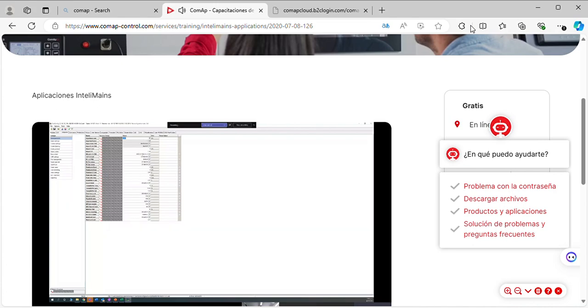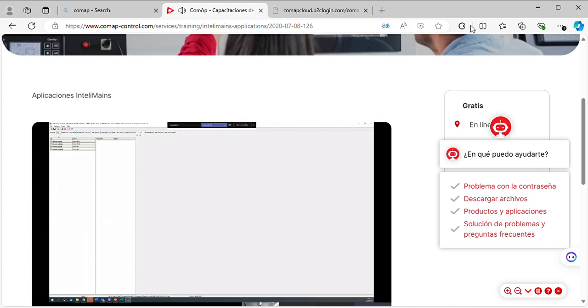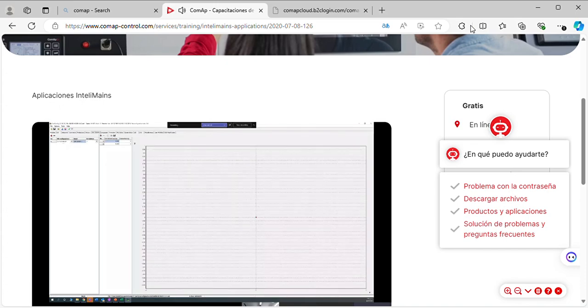Once I have set it here, external, I can go to IO, analog input, and I can choose one of these analog inputs and create a function. If not, I can even make my own user sensor curve, first of all, depending upon the type of potentiometer I'm using. If it is a resistive potentiometer and I name it base load, I can set the resolution accordingly.